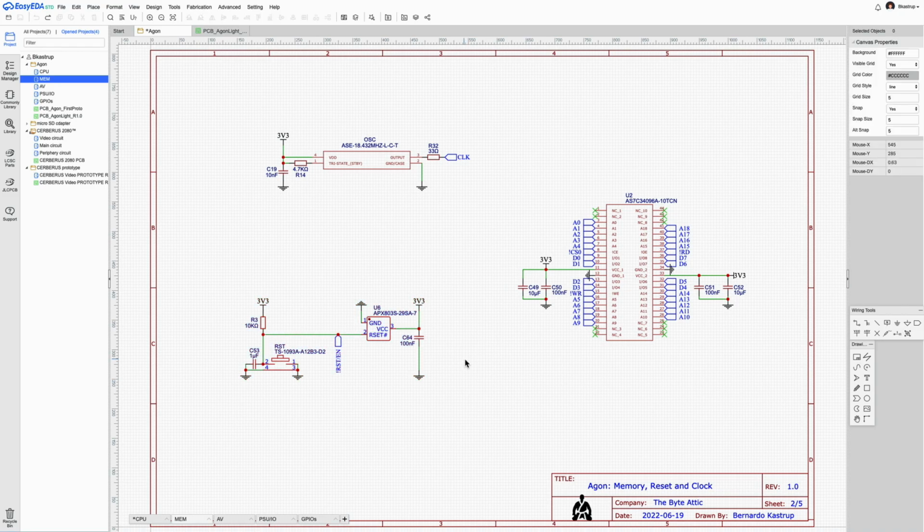Now this is the reset circuitry. It's a very simple open collector circuit. The way this works, let's ignore this part for now. Let's leave that out. Let's focus on this part here. This is just a startup reset timer. When a computer is turned on, this capacitor here is discharged. So current will flow slowly from 3.3 volts through this large resistor here. So small current will trickle through this large resistor and charge this capacitor.